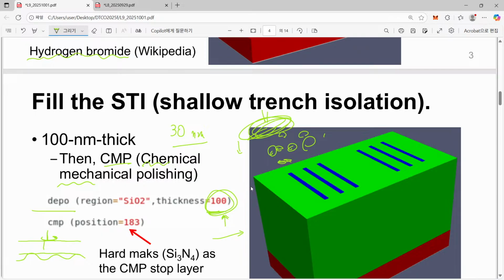After a little while, we can advance a little bit more. So depending on the composition of our surface, the speed of CMP advancement is really dependent. If it is an easy material, then it can advance quite fast. And if it is a difficult material, not that effective in this CMP process, then advancement will be quite slow.